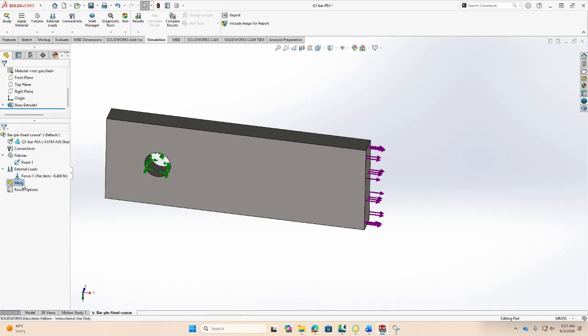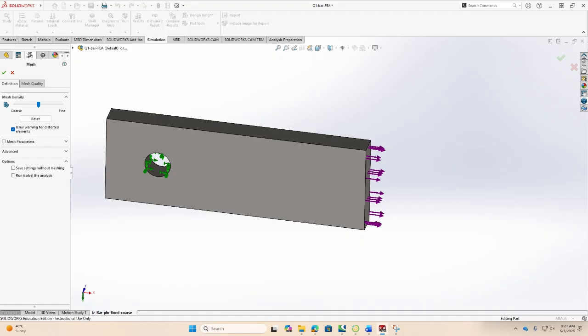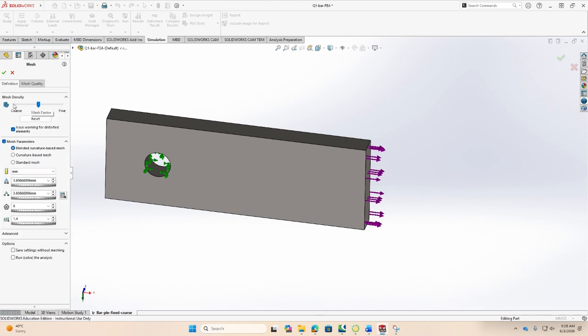Then after this I need to of course mesh it. Now I can go through the whole process again of the mesh convergence and everything. But because this is a very similar kind of structure like the last, the only difference is there the holes were on the sides in the form of notch. Here it is in the middle. So I expect similar sort of behavior. So what I will do is I will just directly start from my mesh control option. I'll use a standard mesh.